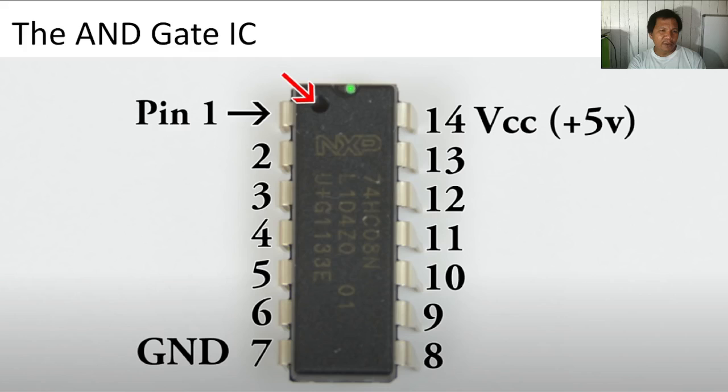We call this one here the notch. Sometimes the IC has no hole. So if you have the notch, from the viewer's view, the left side of the notch is where you have your pin number 1. Later on we will discuss that.